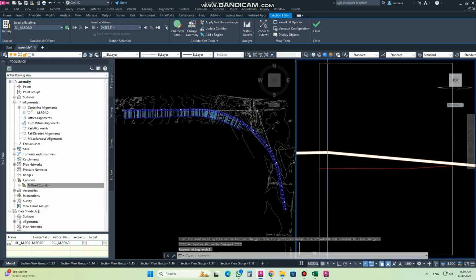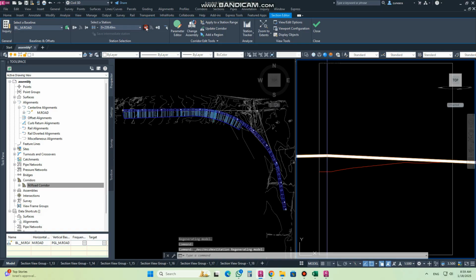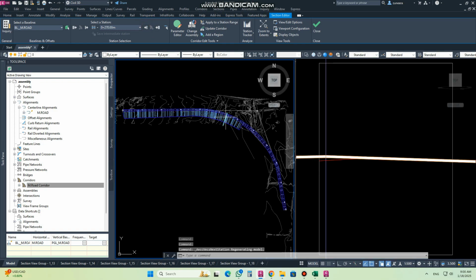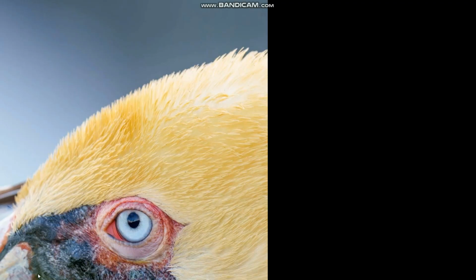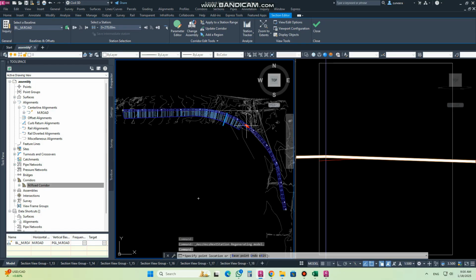Also, sometimes if you don't see the code or link names, it means you are in layout mode and your code is unchecked. So always select the road mode if you want to see your offset, elevation, target, and so on. Also, if you want to create more shapes, you can create them by point and link, and then you can save this. Okay.